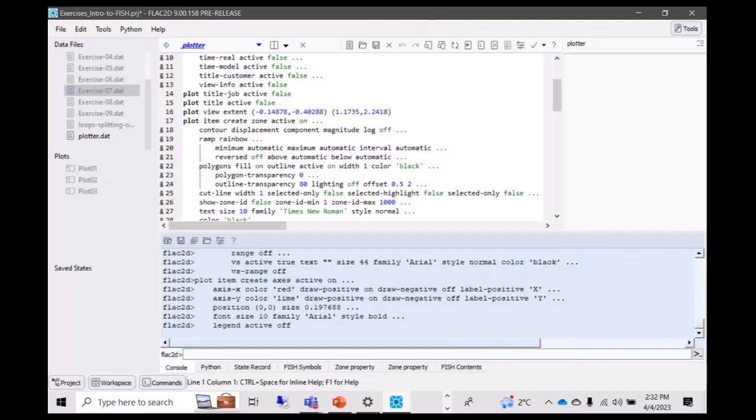But anyhow, between commands, you can use FISH functions. I used to write FISH functions that would step 1,000 steps and then spit out a bitmap, and then loop, step another 1,000 steps until some end condition. So once I get to 50,000 steps, I'm done. That's what I need.